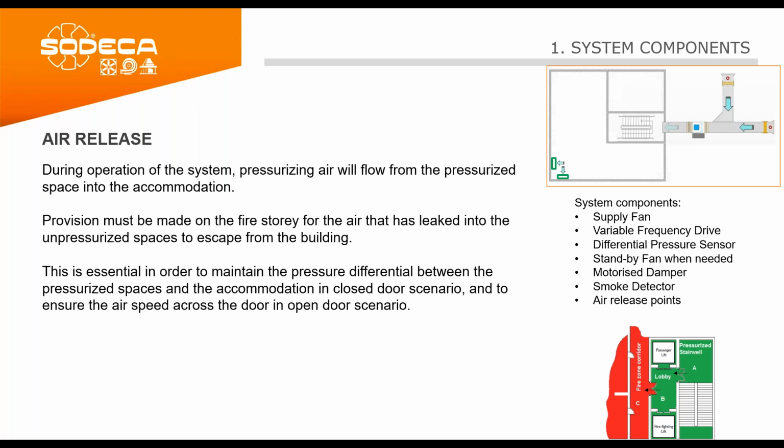So during the operation of the system, pressurizing airflow will flow from the pressurized space, the stairwell, into the accommodation. So provision must be made on the fire story for the air that has leaked into the unpressurized accommodation area to escape from the building.